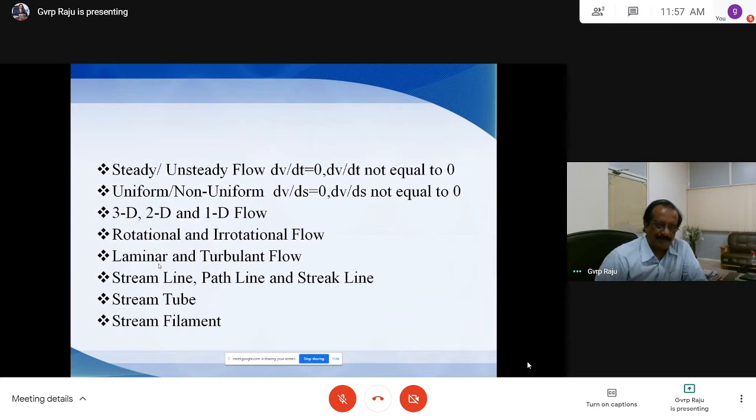When the fluid, while moving, has irregularities, erratic motion, eddy formation, intermingling of the fluid particles, all sorts of disturbance, erratic flow, irregular, and you can expect flow in reverse, etc. Highly irregular, erratic, and intermixing of particles, this side and that side, top to bottom and bottom to top. That you can say is a turbulent flow.